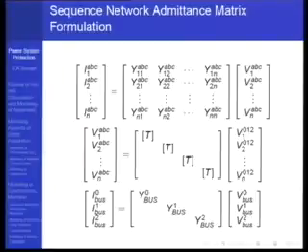Now let us look at this, the Y bus matrix in the 3-phase domain. Each of these entries here is a 3x3 matrix. This Y bus is created using the normal rules of the admittance matrix formulation, except that everything here is a 3x3 entry. Now you apply sequence transformation on ABC here, and then rearrange the equations appropriately, that is, segregate and decouple the zero sequence, positive sequence, moving these variables correctly.